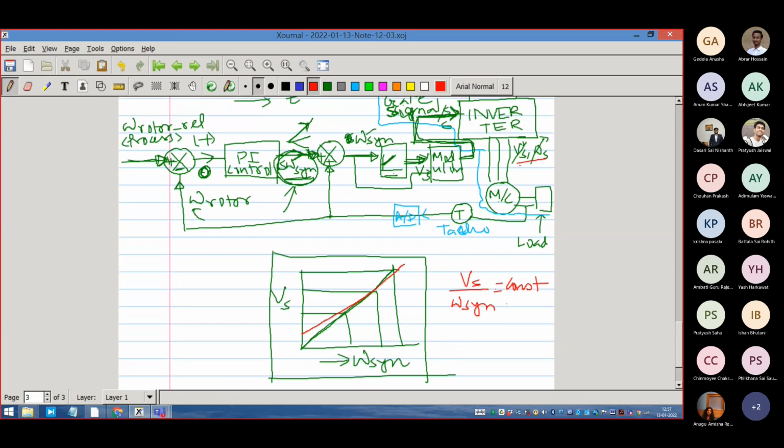What we will be producing is a switching waveform, whose effect will be that of a sinusoid, which will behave like a sinusoid, which is actually a switching waveform, but many pulsed, many times chopped in a 50 hertz cycle or 60 hertz cycle or whatever fundamental period. It will be many times chopped in order to produce an effective sine wave. Okay, though shape wise it is not a sine wave. I am again repeating, shape wise it is not a sine wave, but we will be producing such a waveform which effectively acts like a sine wave to the machine.